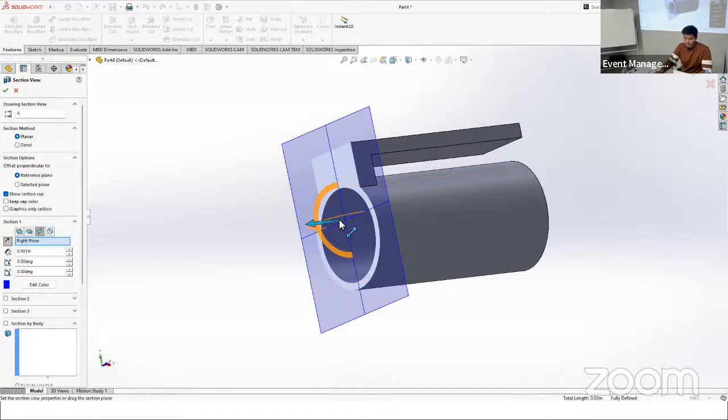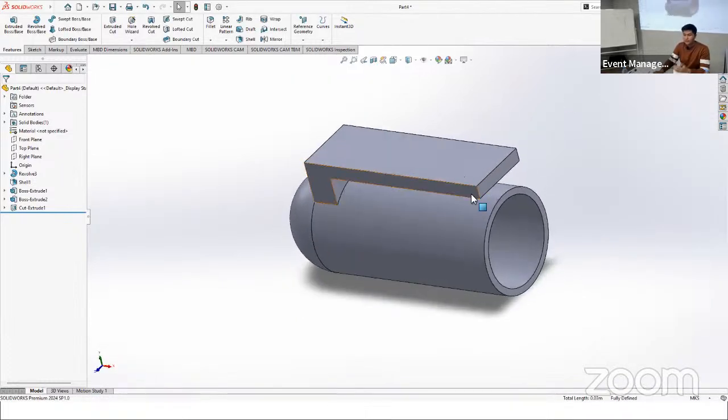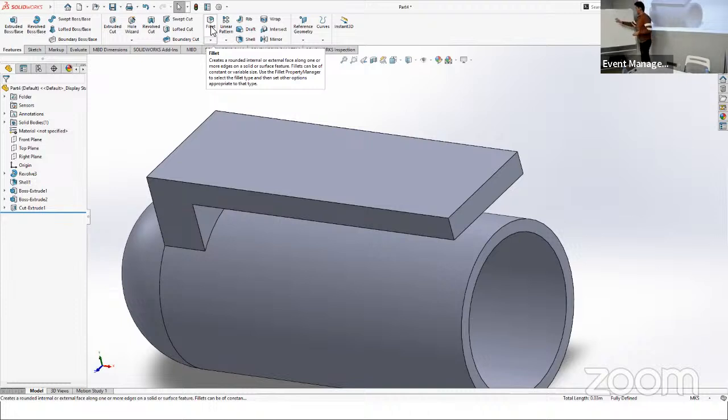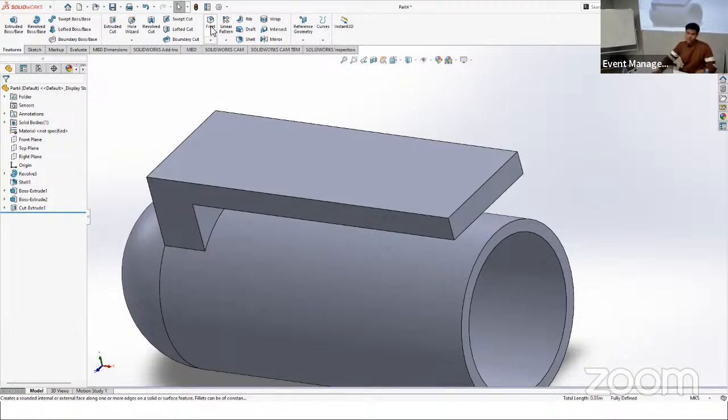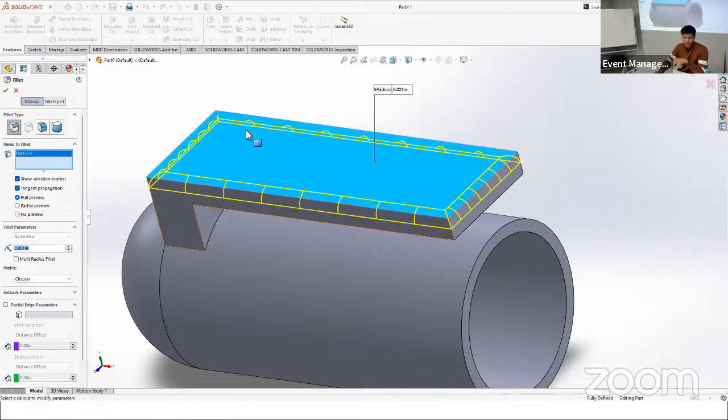Right now it's resolved, but in terms of usability, this part is very sharp. Don't you think so? It may cut your hand or paper. So you can just fillet it. As I mentioned before, a chamfer just cuts at some angle, but a fillet is going to make it round. So something like that. That's what we need. We need some smoothness, so we can just choose that tool. So radius, since its thickness was how many? 2 millimeters. Yeah, we can make its radius 1 millimeter, which is going to be ideal. You can just select the top part, and it's going to create that.